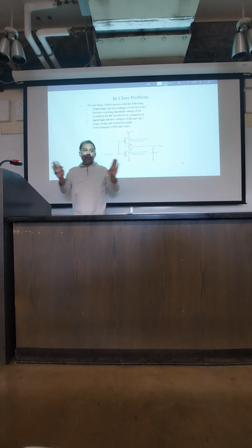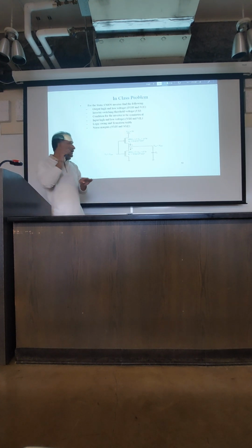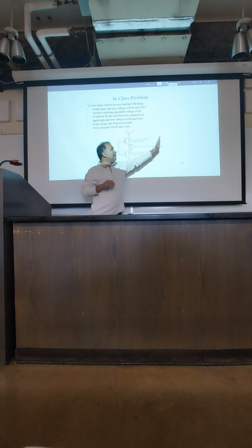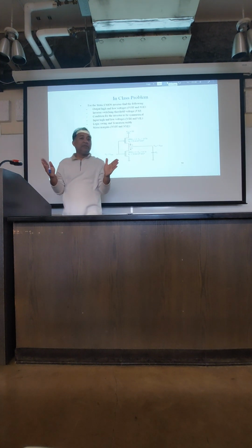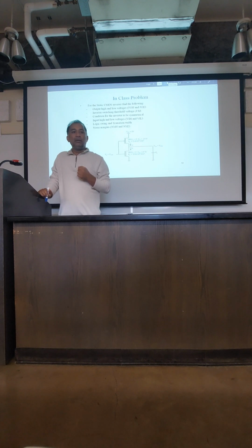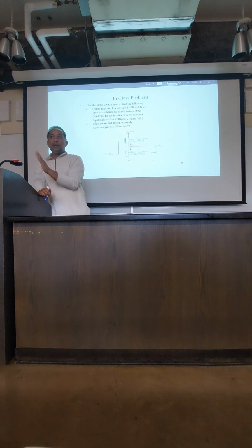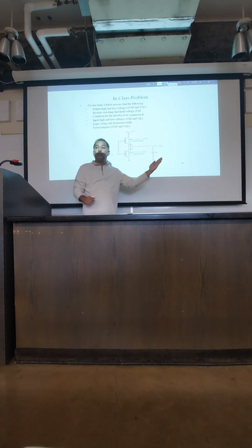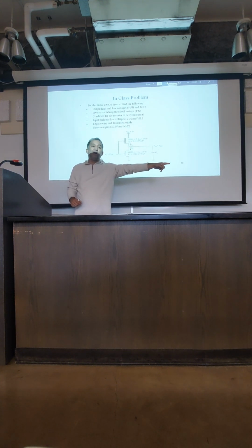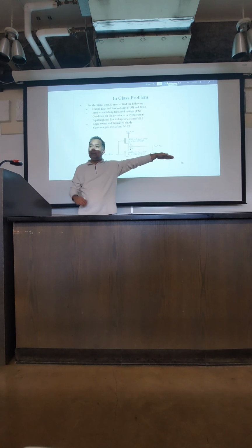Between these two phenomena, application of the input or injection of the input and availability of the output at its desired level, there is a time difference. That is called signal propagation delay. The time it takes for the signal to travel from the input terminal to the output terminal to change the output to its desired value in response to the input.